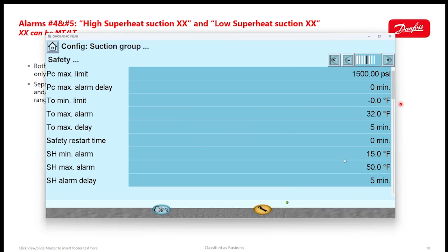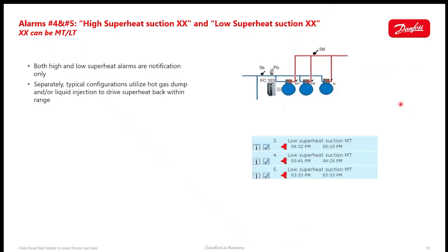Drop this from 90 down to 50. So if we were to go below the 15 or above the 50 here with a 5-minute delay, that will generate these two alarms. No action taken directly here.